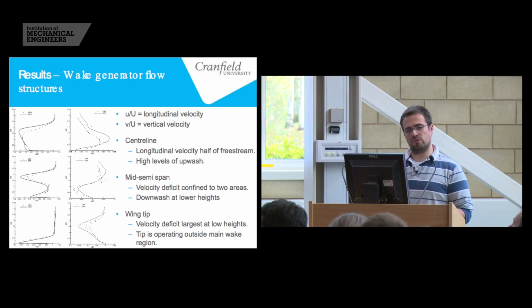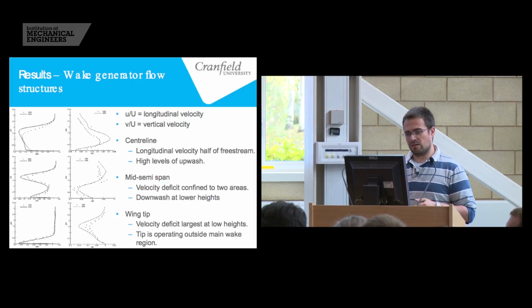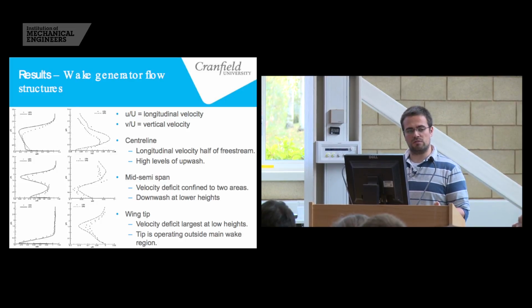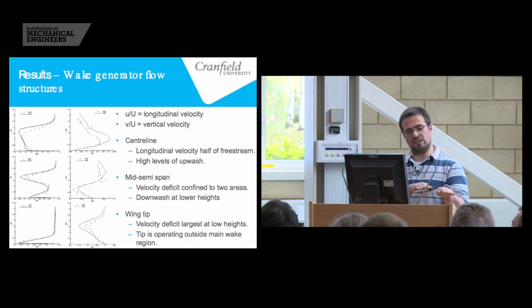In the middle, when we have upwash, we're reducing the angle of attack, while at the tip, we're actually increasing the angle of attack of the wing. Now, you can see this in IndyCar quite well. When two drivers are behind each other, the trailing car tends to offset itself slightly to use the downwash from its rear wing to gain some front downforce.